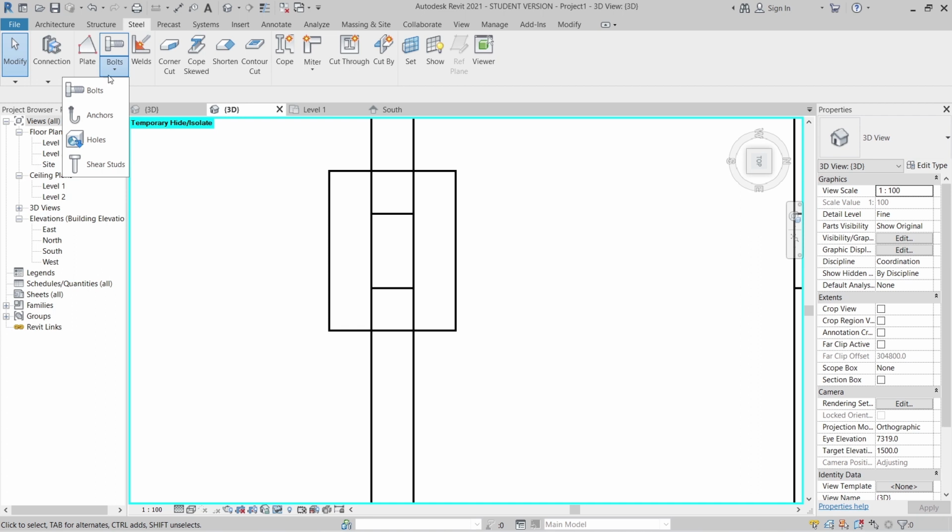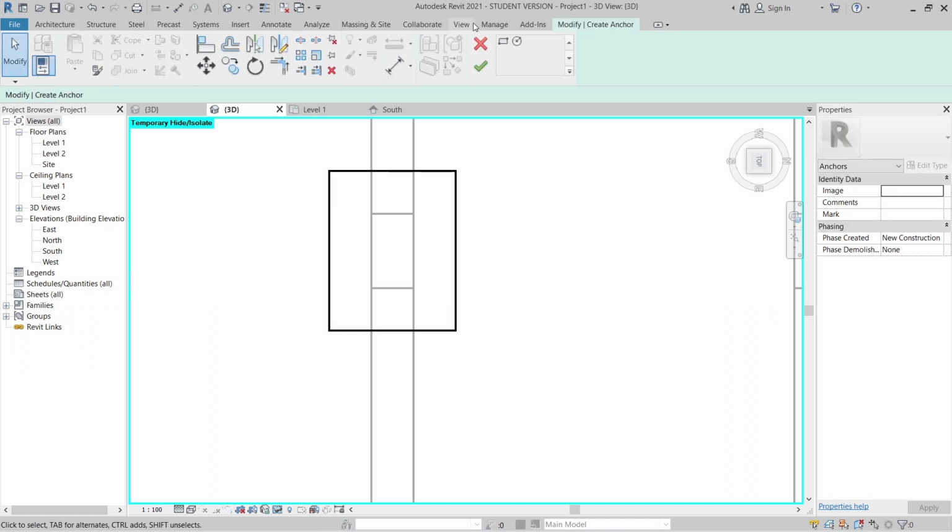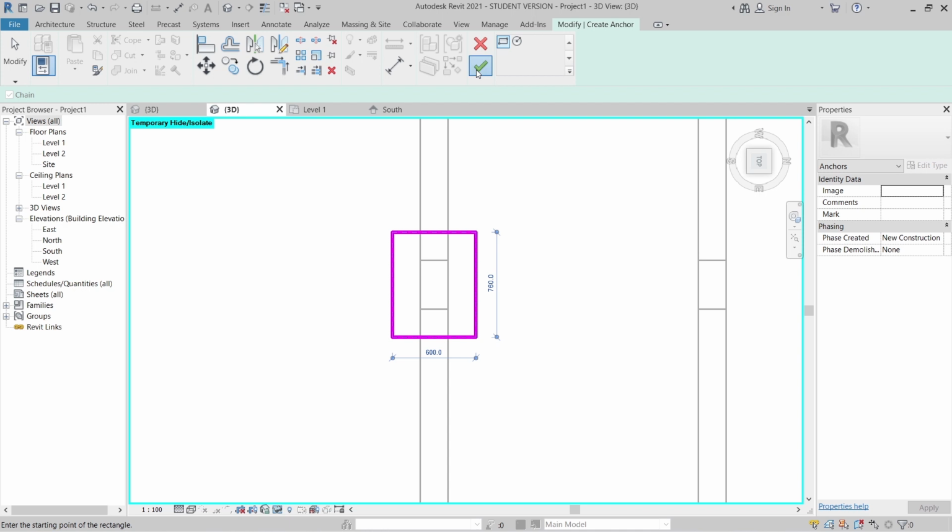I'm going to pick here angle and select my steel plate here. Remember to hit enter on the keyboard and select our steel plate again until you get a highlight like this. Hold highlight on our steel plate. As you can see, now you can apply your angle board on the steel plate here. Then I just hit finish first.